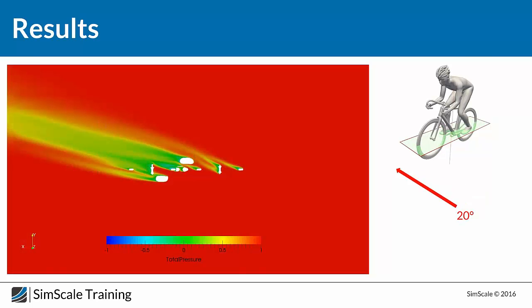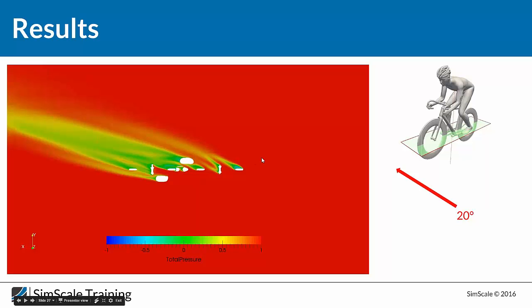So at 20 degrees, there is no way for the flow to stay attached over the tires, and it's completely detached, and the separation is remarkable for the three different designs. And we can see here for high side wind, the flow is totally separated over the large tire or even the mid-sized tire. Maybe Bilal, you have a comment on this one.